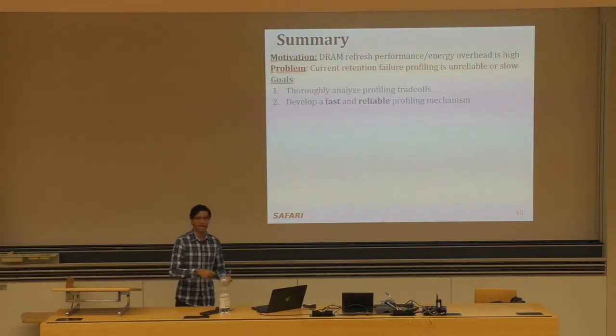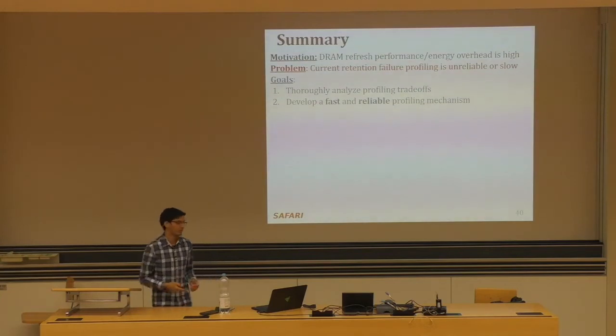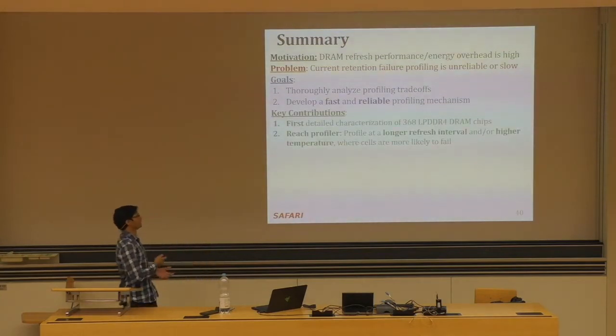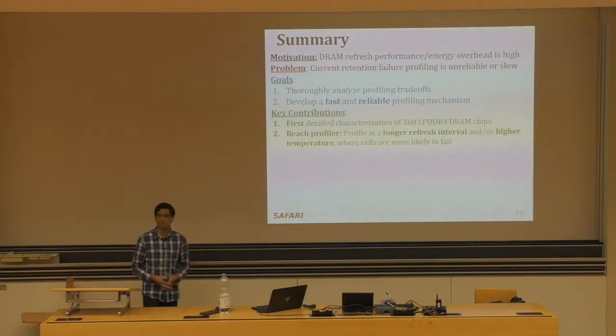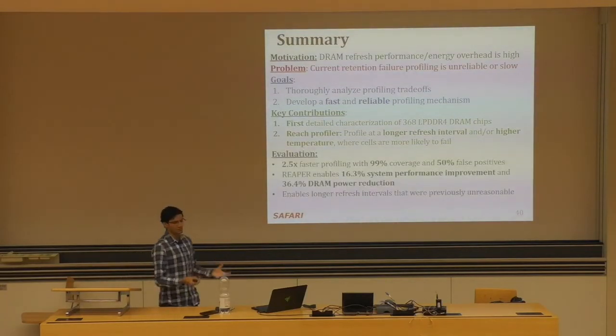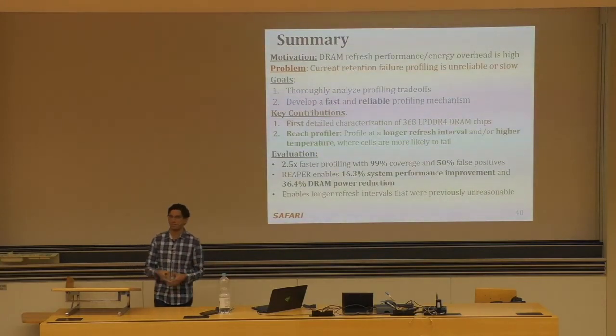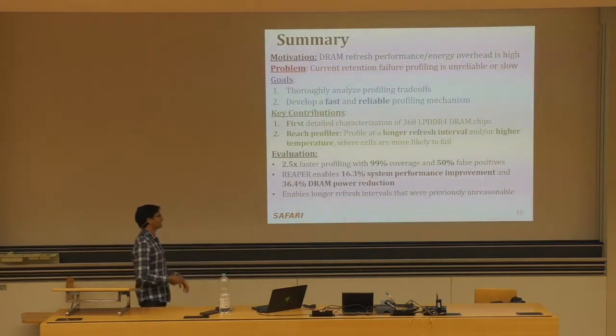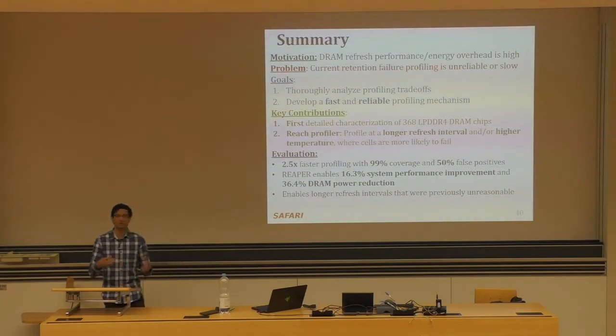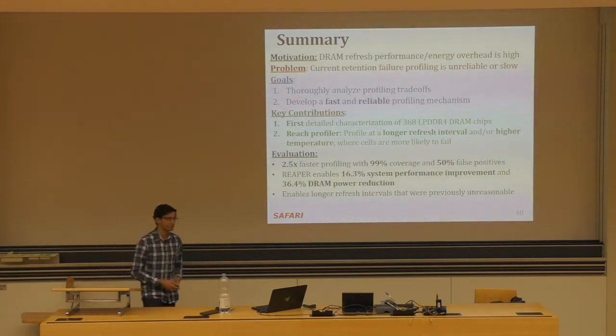And so the goals of this work were to analyze the trade-offs in profiling and then develop a good profiling mechanism based on what we learn. And that's exactly what we do. We perform the first detailed characterization of many different LPDDR4 devices, and we use that to propose the reach profiler. And through our evaluations, we find that the reach profiler achieves a significant profiling speedup at a power consumption improvement, and it actually enables longer refresh intervals that are unreasonable with previous approaches.